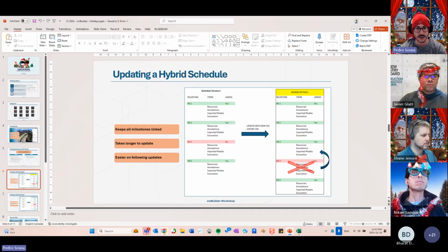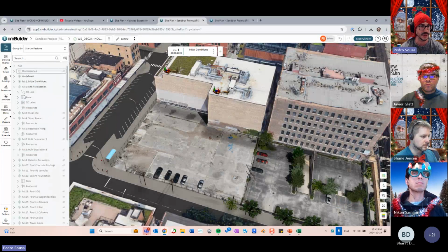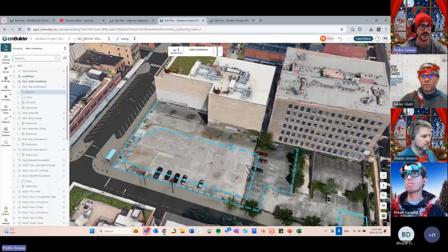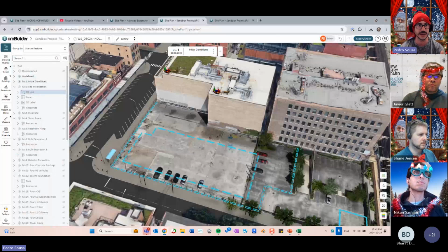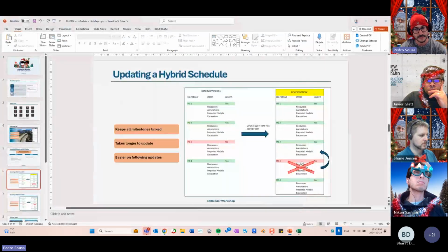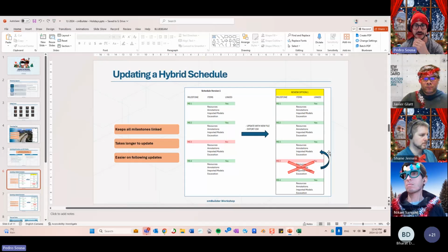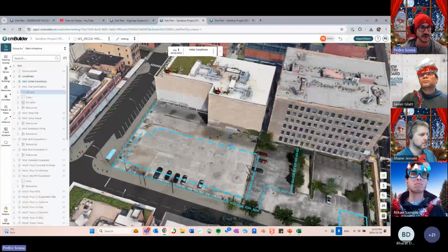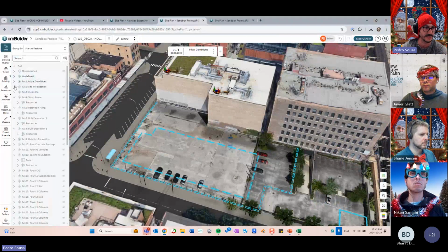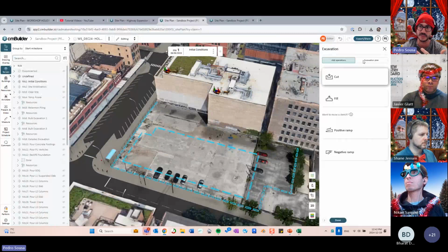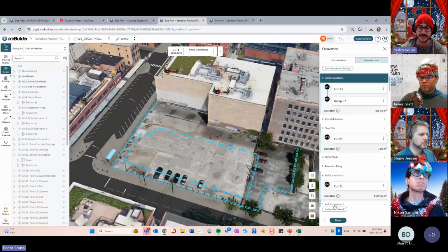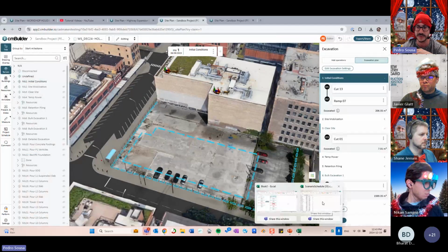To do that, using this kind of view over here is perfect because you can select the group of parts and then just activate the other milestone and say all of these will show up at this date. So it's very easy to do, but it will take longer depending on how many manual milestones you have in your file. The only thing you won't be able to use that view for, with the start milestone, is the excavation operations, because the excavation you need to adjust from your excavation plan, right? So then you would need to move the operations to the new milestone from here.